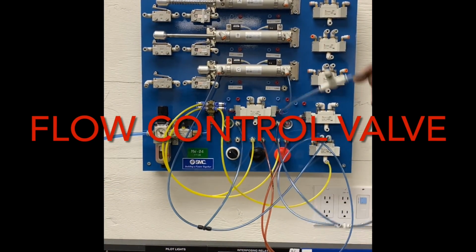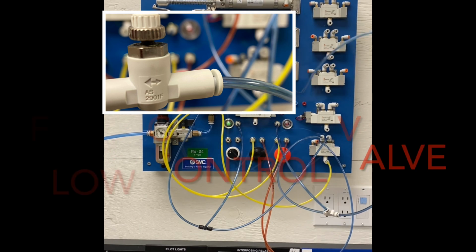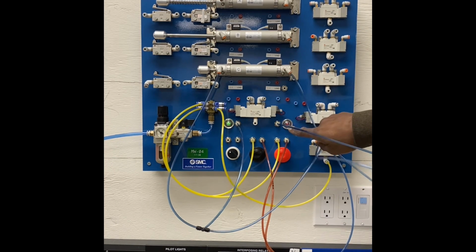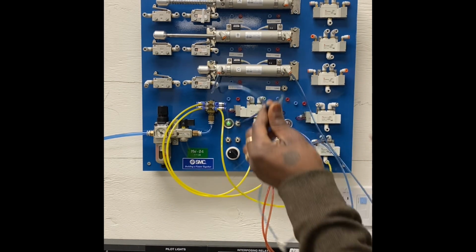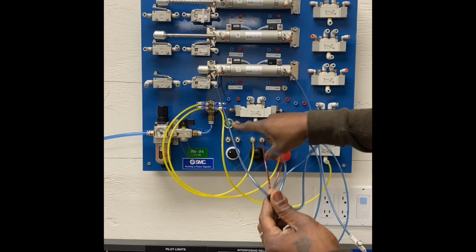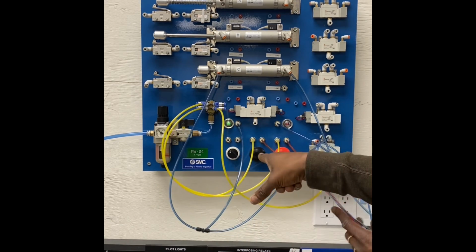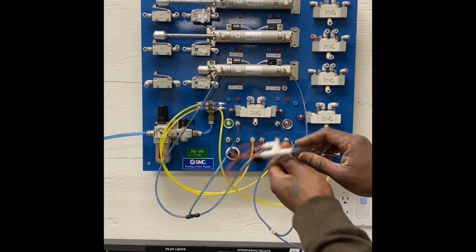Let's introduce another control element, the flow control valve with check bypass. The flow control valve is connected to the cap end of the double acting cylinder in a meter-in arrangement. So what do we mean by metering in arrangement?